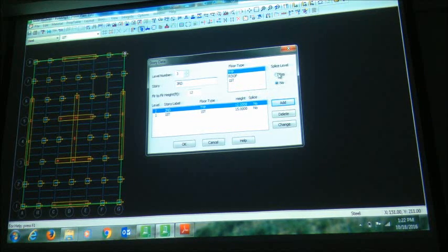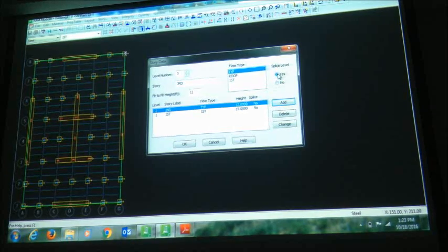typical. Only thing in the change is I will change splice. Splice means after the third floor level, I will change my column size. That's what splicing means. I can change my column size. Usually the members come about 40 feet, almost like 45, 40 feet. So 24, 12, 15, which is 39 feet. Yeah. That makes sense.